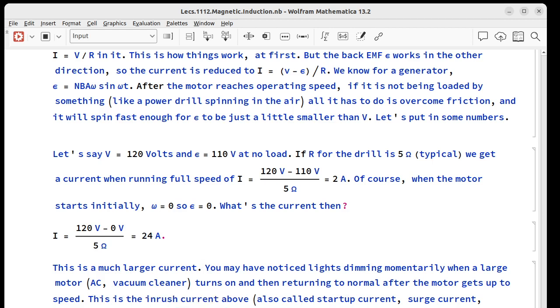Most of the circuit breakers in your electrical box are probably 15 amps for wall outlets. If they tripped instantly once you got to 15.1 amps, you'd never be able to use anything with an electric motor, because startup would cause it to trip every time. You don't need them to work this way, because what you're trying to do with the breakers is keep the wire in the house from catching on fire. And 1 second of high current, if it's only this high, is not going to cause a fire.